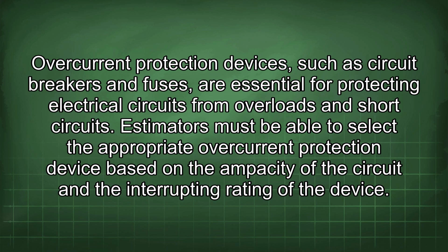Overcurrent protection devices, such as circuit breakers and fuses, are essential for protecting electrical circuits from overloads and short circuits. Estimators must be able to select the appropriate overcurrent protection device based on the ampacity of the circuit and the interrupting rating of the device.